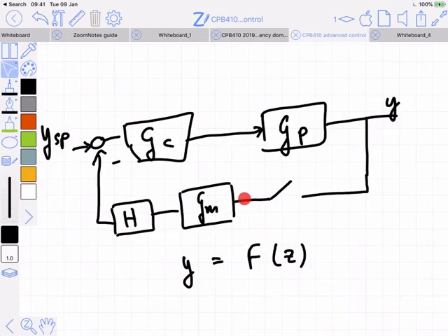So it is reasonable to ask for an expression in terms of Z that will tell me what the values of that sampled signal are. But that function will change for every different YSP, and you'd have to calculate the Z transform of that whole function instead of going as a transfer function.